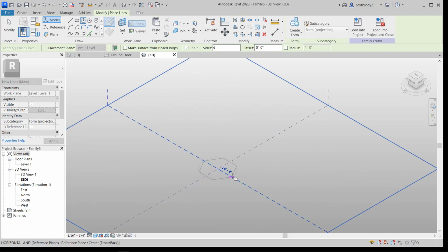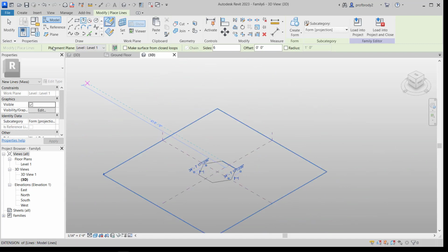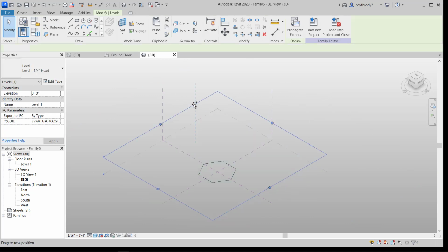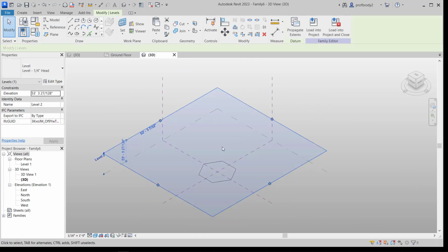And note the scale. That says 24. What is that? 20 feet. So these are big objects. Okay, they're meant to be buildings. The trick here is I can create additional reference planes by just copying these reference planes that are here.